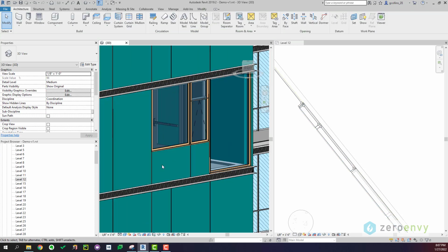So we will use doors. There are different approaches on how to deal with spandrel panels. Our go-to approach is just use doors because I think it's pretty hard to split a wall into multiple pieces and assign thermal constructions to them. The more straightforward way would be just using a door to represent spandrel panels, and you can create a unique construction for the door. So we will do that in Revit as well.